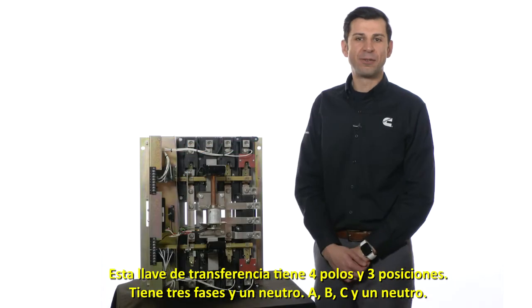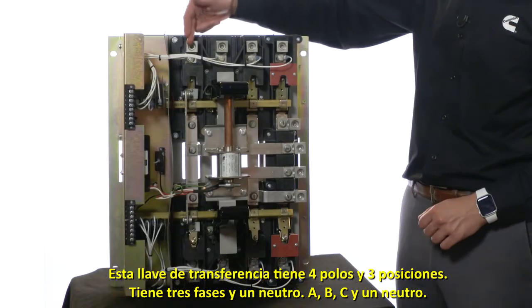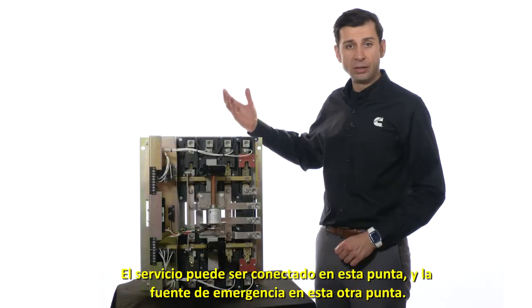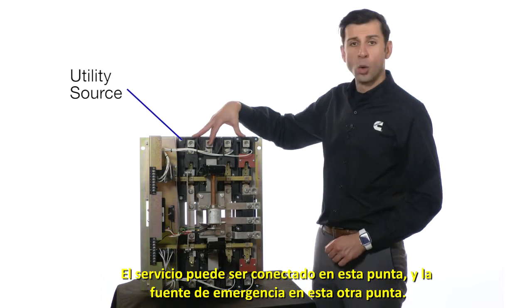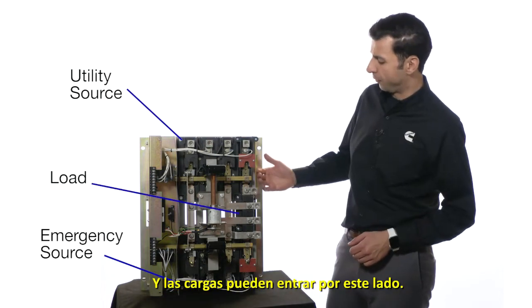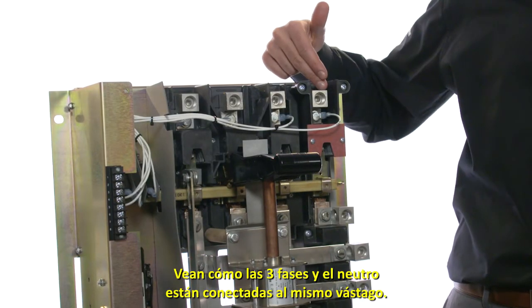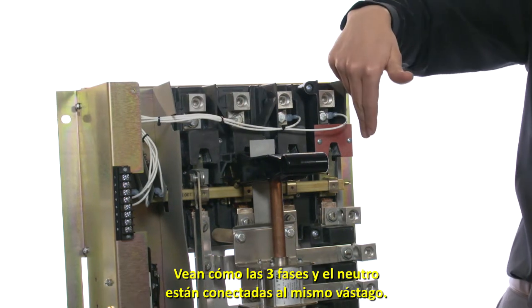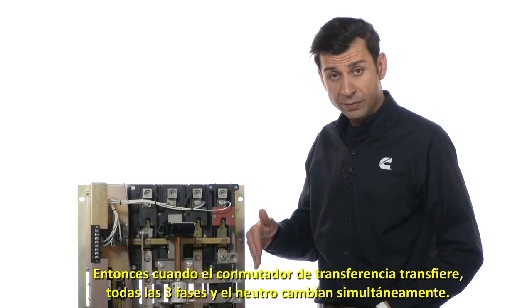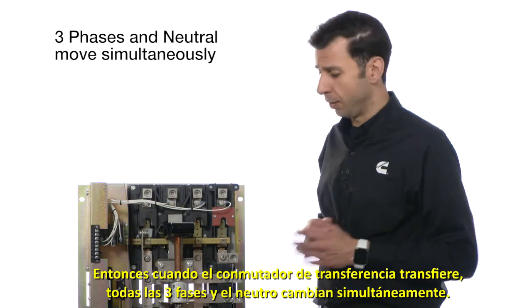This transfer switch is a 4-pole, 3-position transfer switch. 3 phases and a neutral, A, B, C, and a neutral. The utility can be connected on this end, while the emergency source can be connected on this end, and the loads are fed from this end. Notice how the 3 phases and the neutral are connected to the same connecting rod. So when the transfer switch transfers, all 3 phases and the neutral are moved simultaneously.